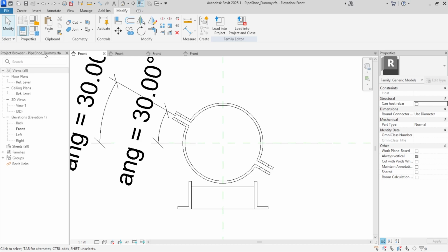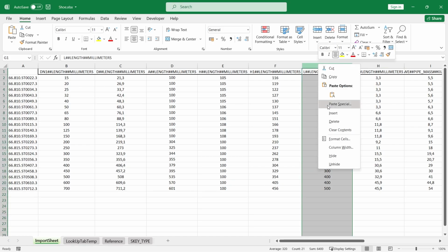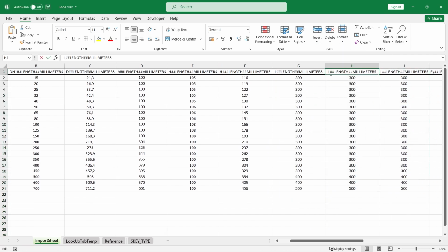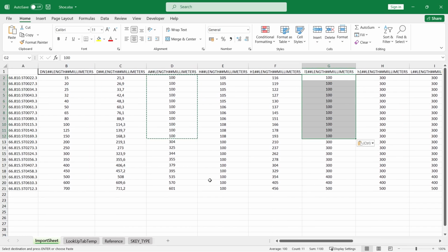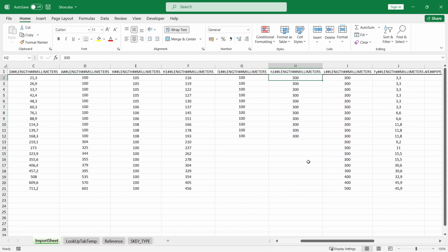As we are ready with the main geometry, let's fine-tune some places. As we are missing a few dimensions from the vendor catalog, we will measure them from the model and add them to our lookup table by adding 2 additional columns. We need to do it only for DN 200 and above, as we are facing this issue only with the L profile.